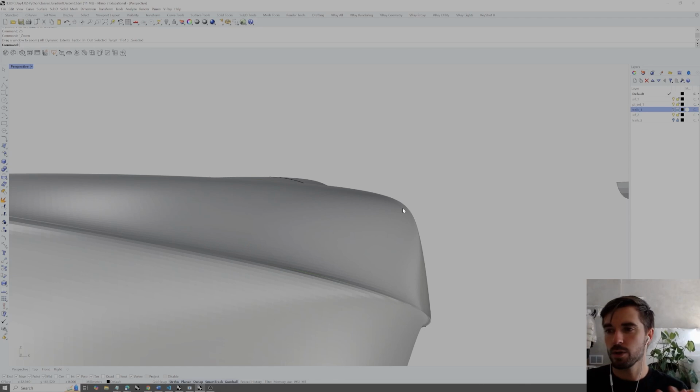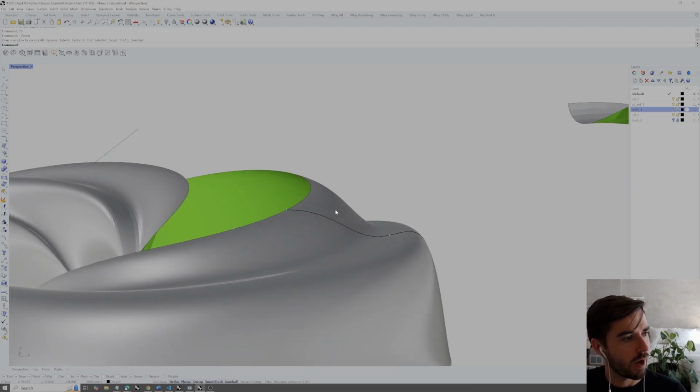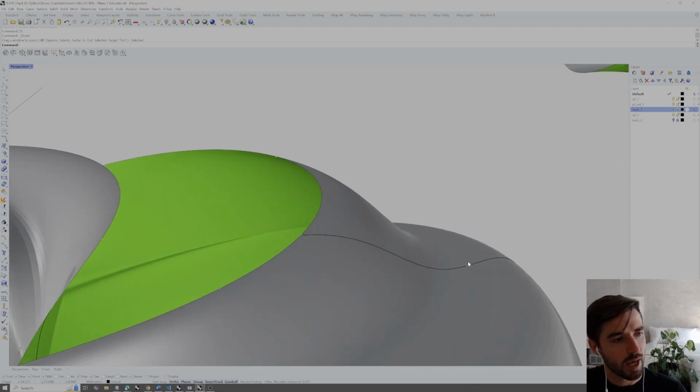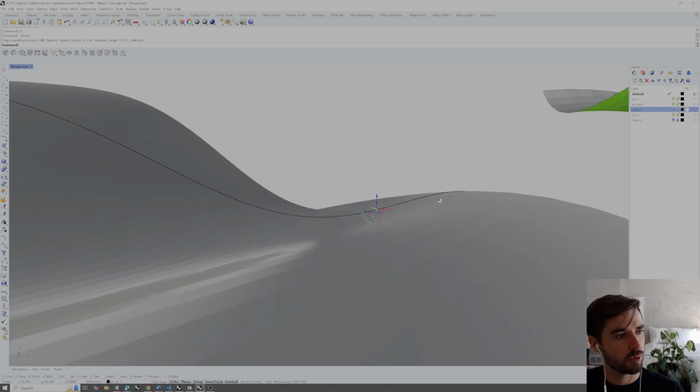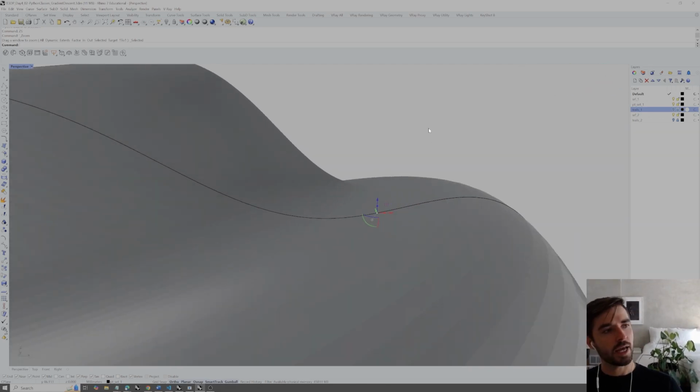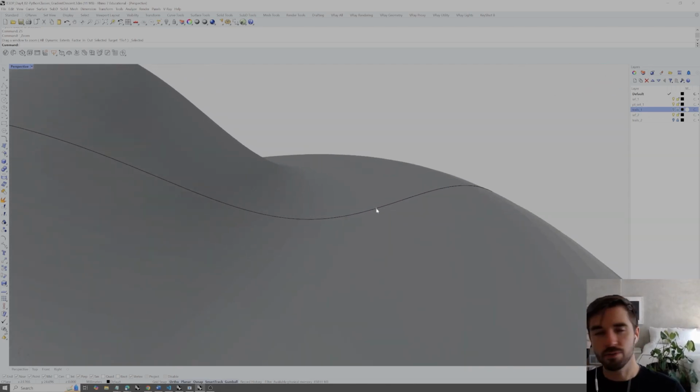Now, to get that curvature or to get that slope of our surface, what we have to do first is find that closest point. So snap our point, let's say we're evaluating this point, snap that point to the surface. And now, once we find the closest point on our surface, what do we get as an output there? Well, we get our parameters on our surface, which we can then convert to an actual point. What else can we get from a surface?